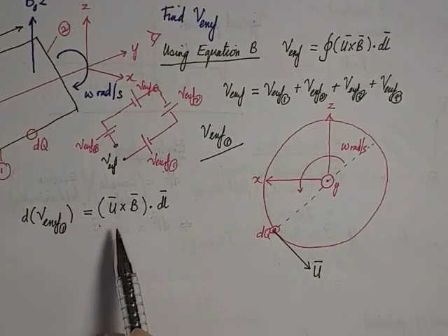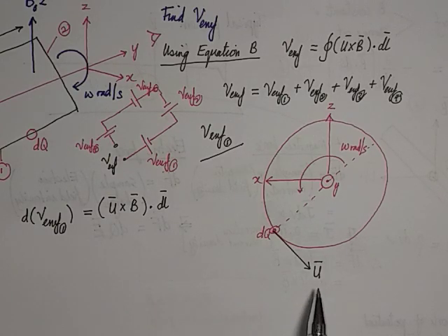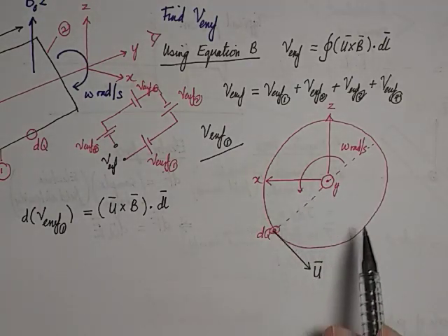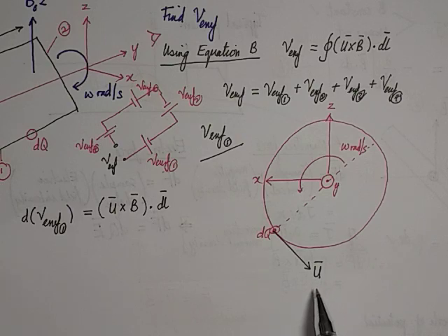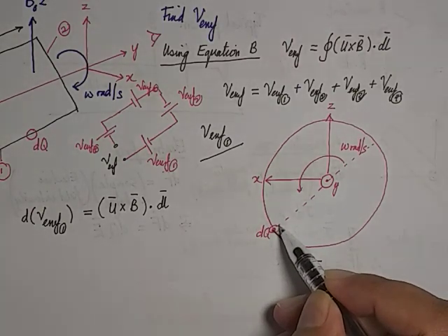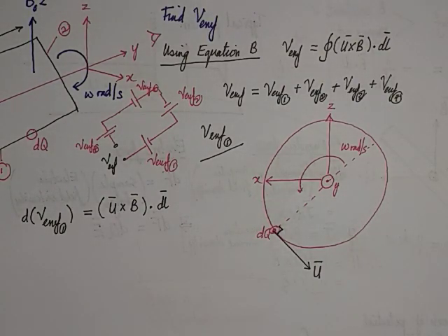The u that you want to define in this equation must be represented in this format, because this is a linear velocity, even though the path number 1 is moving in angular movement. We have to convert to linear velocity. Tangential means that the angle between the u and the radius of the circle is 90 degrees. So that should be u in terms of the diagram.